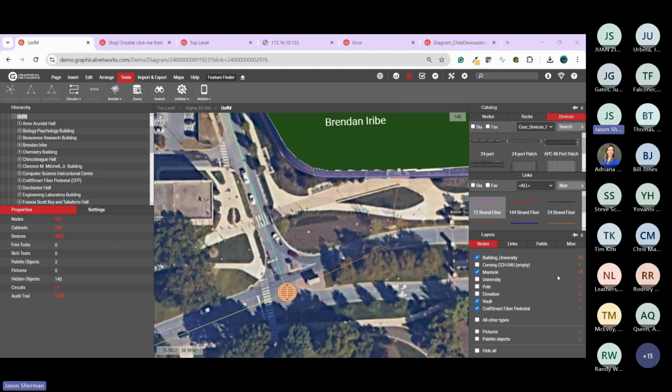Sumitomo air balloon. Yeah, we have a few customers that do the Sumitomo. It says Sumitomo air balloon fiber tube, microducts. So what we typically do there is create different object types. We'll create a microduct object type that becomes a kind of conduit transport. You're going to blow fiber in, so you're going to have fiber cable with strands, 144, 24s, whatever their counts are. I don't remember off the top of my head. And those are all going to terminate to the Sumitomo boxes and things like that. So you can do it. I have some customers who've done it.